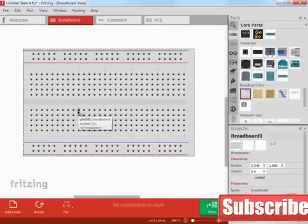The contacts are arranged in rows and columns. Each column, 1 to 30 for this breadboard, has contacts in rows A through E common and contacts in rows F through J common. Any device inserted into the same column in rows A, B, C, D, or E will be connected, and any device inserted into row F, G, H, I, or J will be connected if on the same column. The rows are not connected.